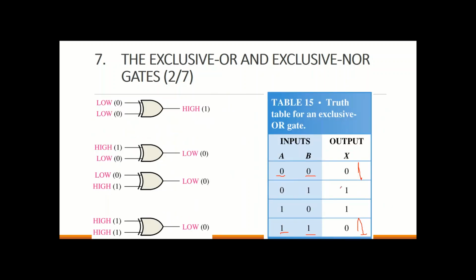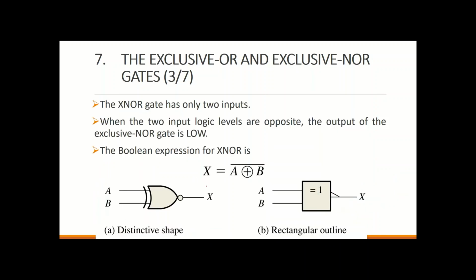Let's say we look for the high state here. What's composing it based on ORing terms? Now look at this. If I put not A and B, it will be 1. So not A and B will guarantee 1 for me. A and not B will also guarantee 1 for me. Sum them up, that means all these terms, not A and B, or A and not B. That's how it is found.